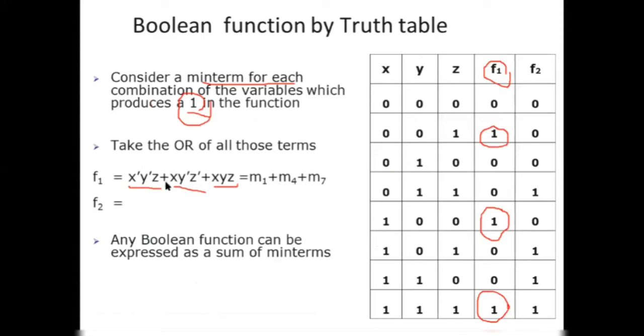And so here we have the OR sign, because we have to write the OR of the min terms as the function at the end. And here we have x, because the value is 1. The other two get primed because they are 0. And in the other term, in 7, you have all the values 1, so you are not going to prime any. Okay?